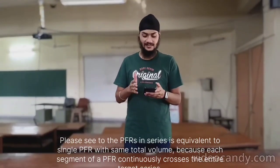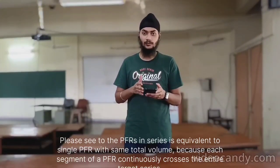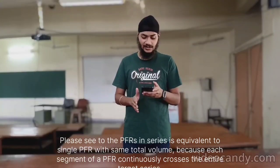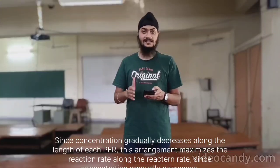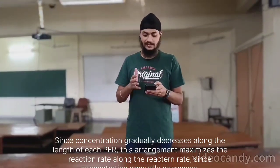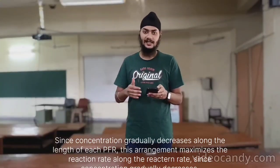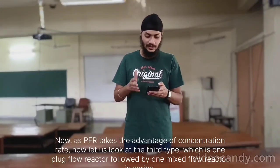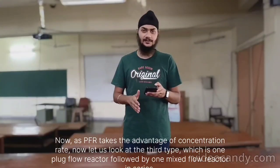Placing two PFRs in series is equivalent to a single PFR with the same total volume, because each segment of a PFR continuously processes reactants without back mixing. Since concentration gradually decreases along the length of each PFR, this arrangement maximizes the reaction rate along the reactor length. PFR takes the advantage of the concentration rate.